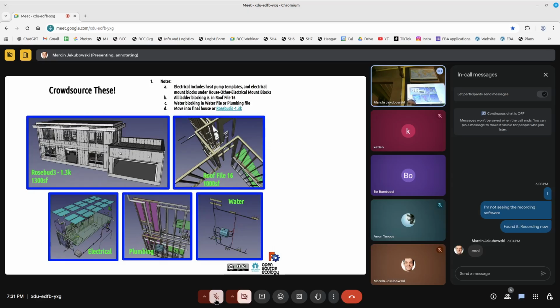Are those behind the wall or on the wall? They're at the bottom of the wall. We basically have drywall, a little bump in there, and a second layer of drywall. I'll talk about that when we talk about the electrical. So you've got a wall, you stop at the 1 foot level where the utility channel is. You put your wires running down there on the surface, no drilling. That's the whole point, no drilling, just lay your wires out and staple them. You can modify that. They're not encapsulated in a metal or plastic case. Nope, just drywall, right behind drywall, but no nails there.